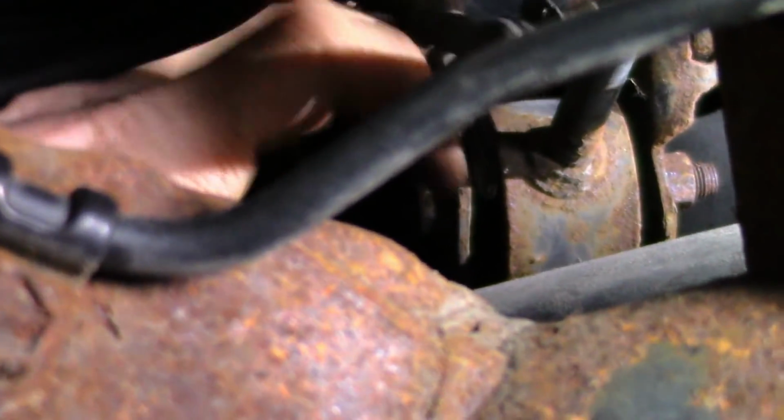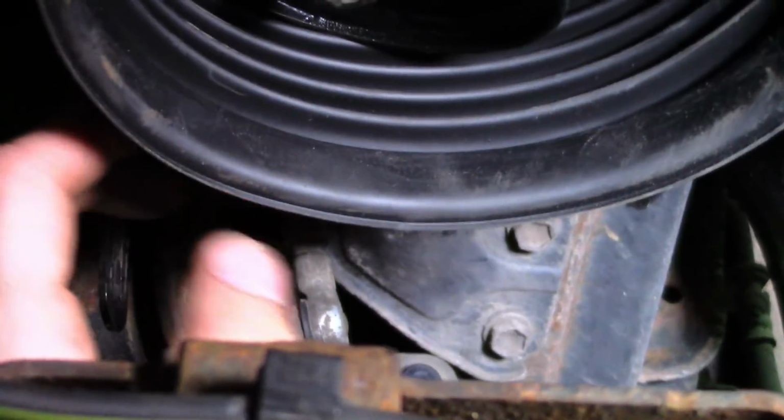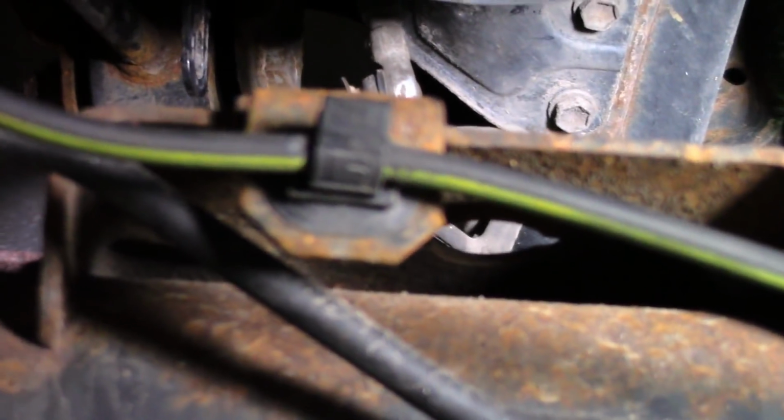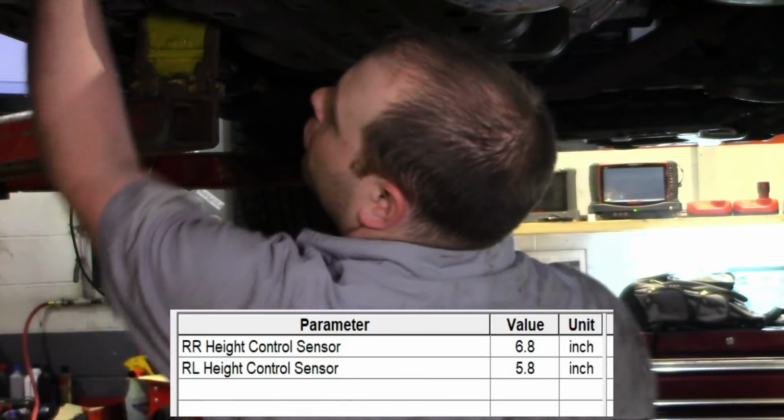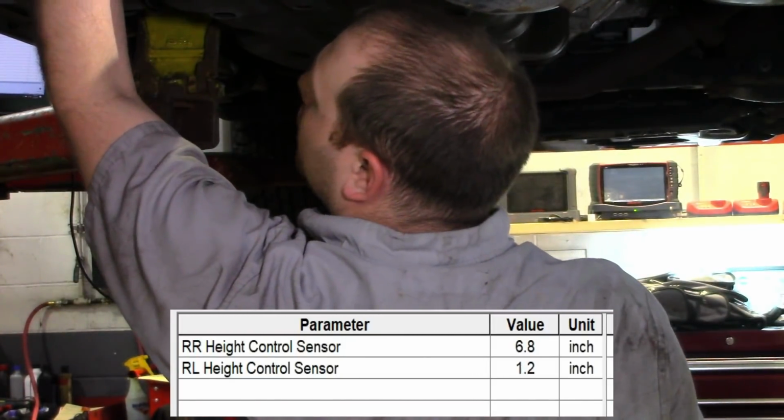So on these rear suspensions, I hope you can see them. I know this is going to be hard to see on the video, but there's 2 height sensors. This here is the left side. I'm going to move these up and down. Watch the data PID. This side's a little easier to see. I'm going to move this one up and down and check the data PID, and I'm going to compare the two to see how much they each move. So I'm going to move these up and down and compare the 2 sides. So that's the left side.